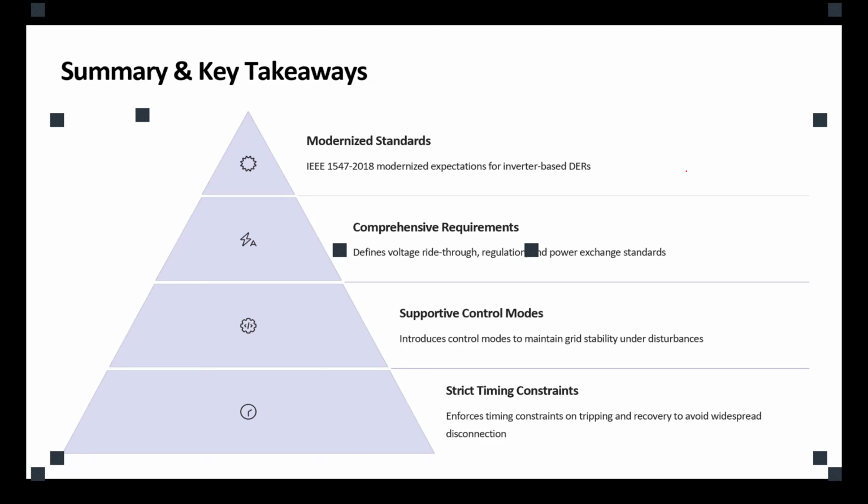For example, in your own model, you have a droop control or a PID for grid following, or a PLL control that works with the ideal situation. Now we are adding another logic by this standard, so they have to contribute to the fault during the fault ride-through.